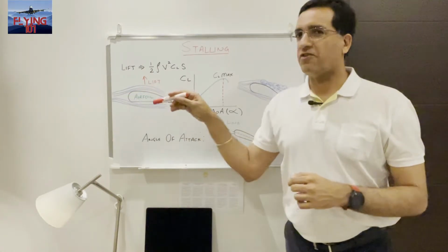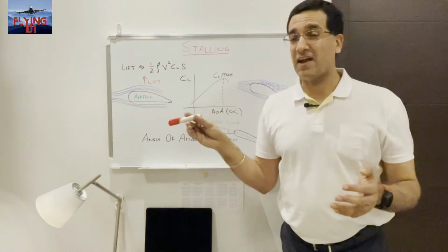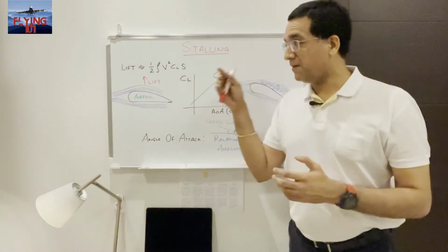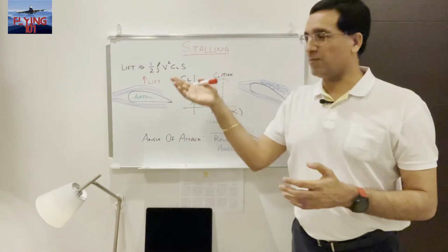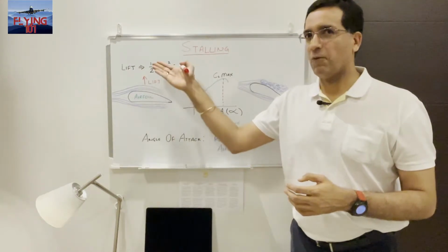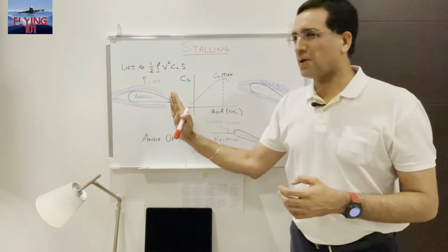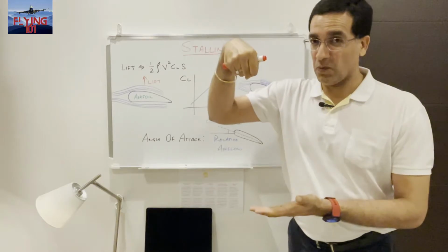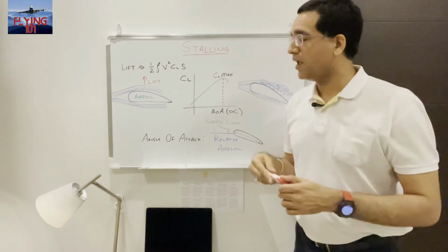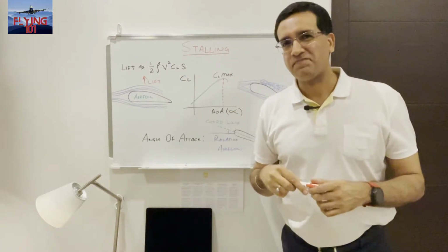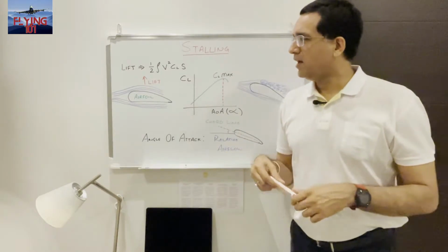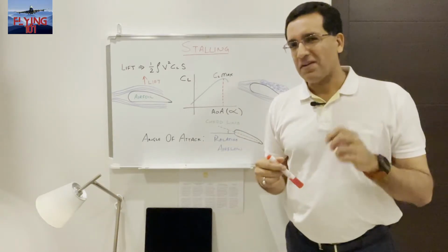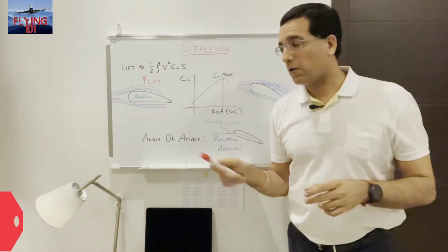It actually causes a drop in the ambient pressure or the static pressure on the top, which in turn creates the lift force, because when we have high pressure on the bottom and we have low pressure on the top, we've then got this upward force, this pull on top of the wing, and that's what creates lift. So having recapped how lift works, now let's take a moment to understand something called angle of attack.